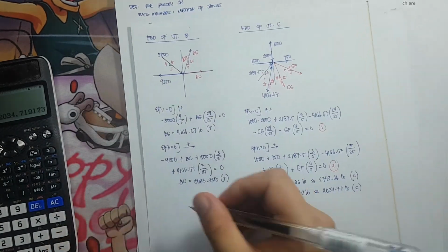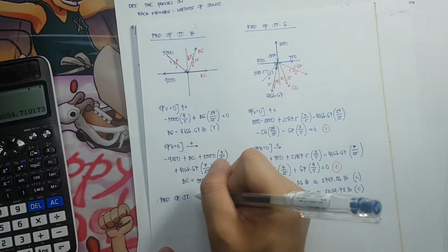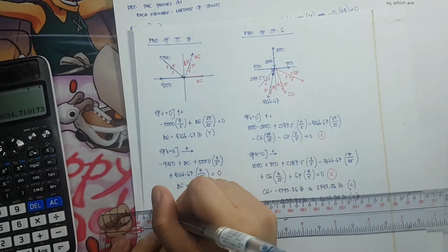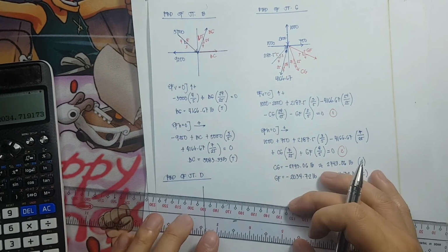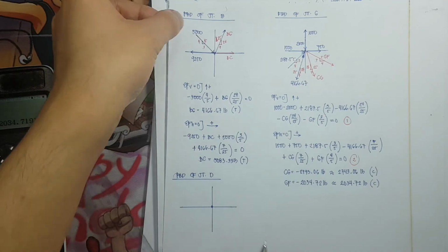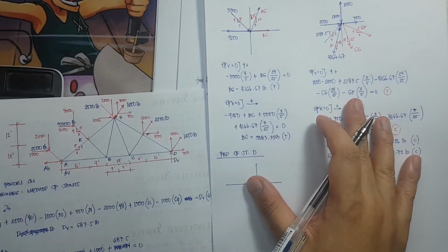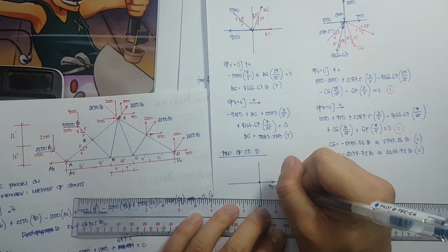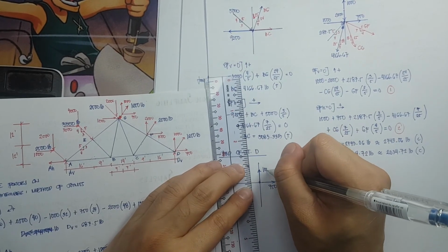Okay. So FBD of joint D. So the free body diagram of D is equivalent to, drawing the joint D, we have this. So this is joint D. So what are the forces present at joint D? So we have here 750. We have here an upward force of 1000.